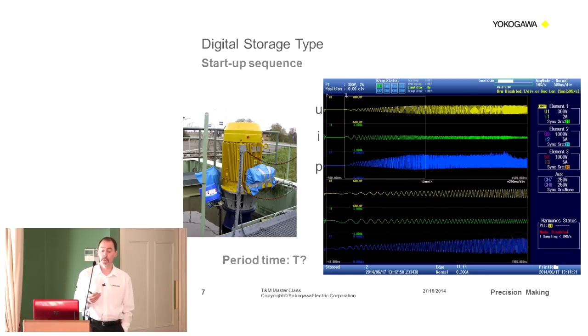So it is, of course, relevant to measure the continuous power, but from a development point of view, the engineer may also want to look at what happens when a particular part of the process kicks in. What effect does that have on the power? A traditional power meter won't allow you to do that, because it's essentially not transient based. You can see, as we have an example here of a motor, that as the motor kicks in you have a changing cycle. So it would be no use measuring the average power over a longer period. It's not going to give you any sensible result.